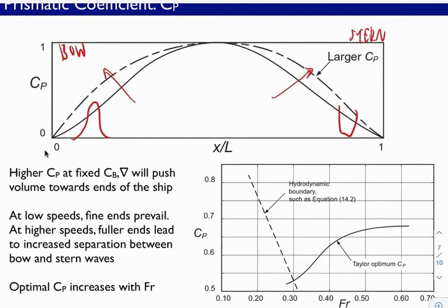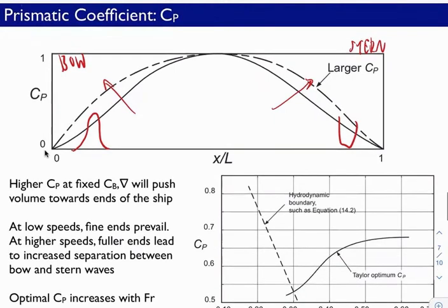the wave resistance, as we talked about when we were looking at how Froude number comes into play with wave resistance. What happens is even for a given length boat, by making it fuller at the ends, where the bow wave is manufactured and where the stern wave is manufactured gets spread out.